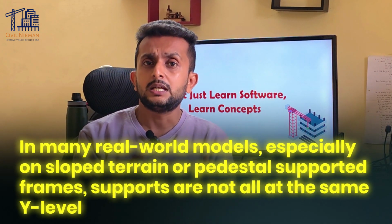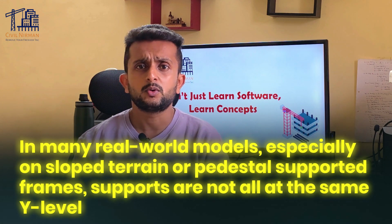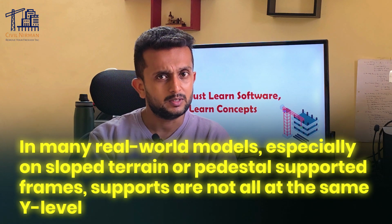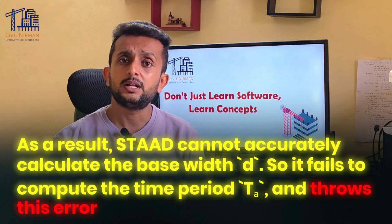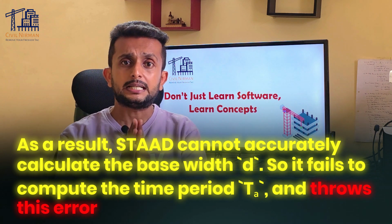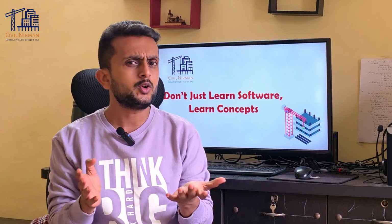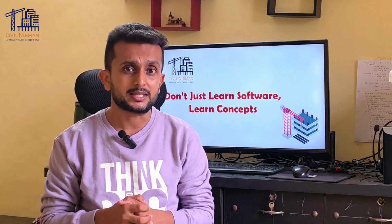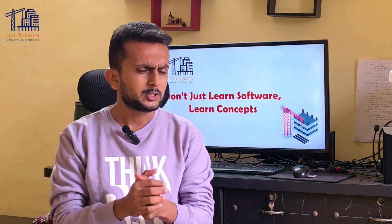In many real-world models, especially on sloped terrain or pedestal supported frames, supports are not all at the same level, right? As a result, STAAD cannot accurately calculate the base dimension width D, so it fails to compute the time period T and throws this particular error. So it's not about a wrong command, it's about STAAD not being able to extract reliable geometrical data. Now let's talk about the solution part.